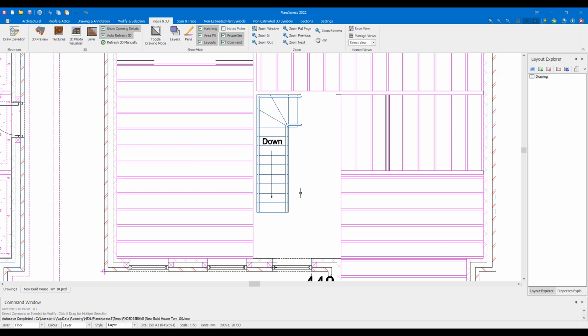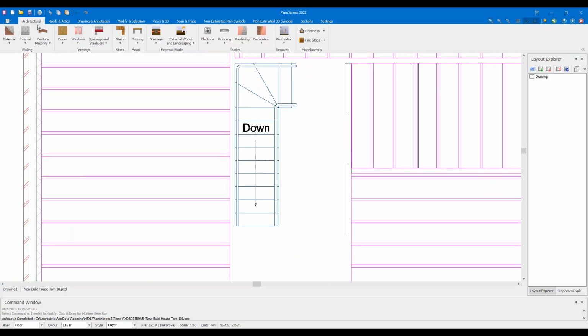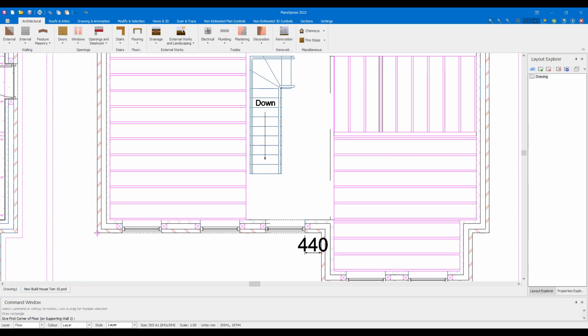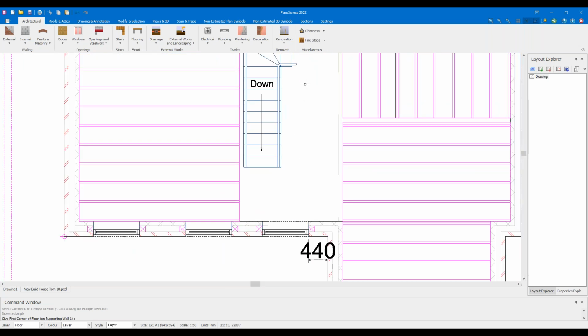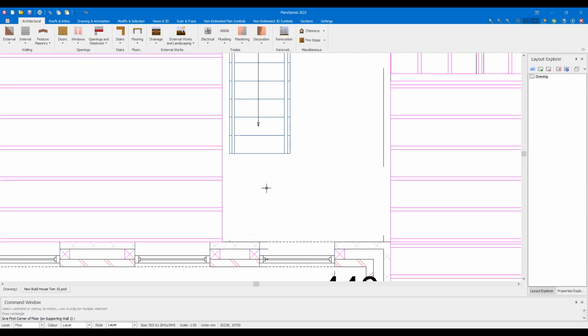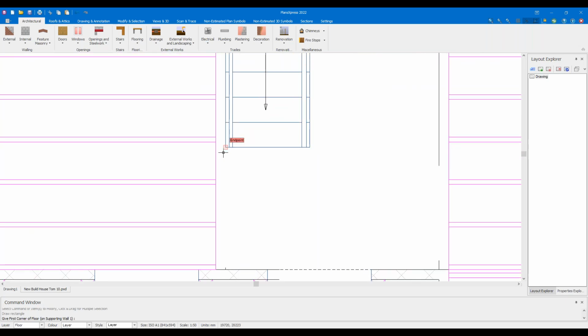Right, now those stairs should be edited. I'm going to go back, grab my flooring tool, just click on the icon since the settings are going to be prepped. If you remember the last one I used under flooring, and with my tool active, I just need to draw in the last two sections. On the last section, I am going to be saying yes to the additional tools because there are some items I need. So first off, with my tool active, I'm going to draw from this corner